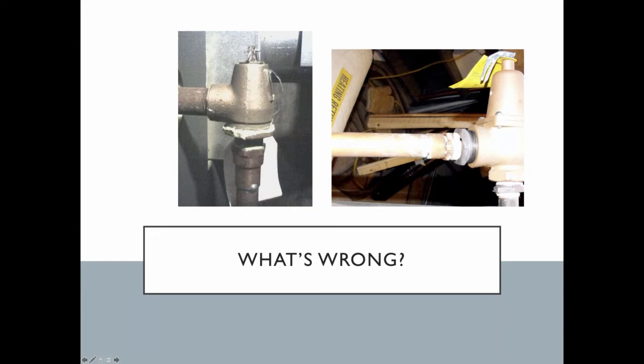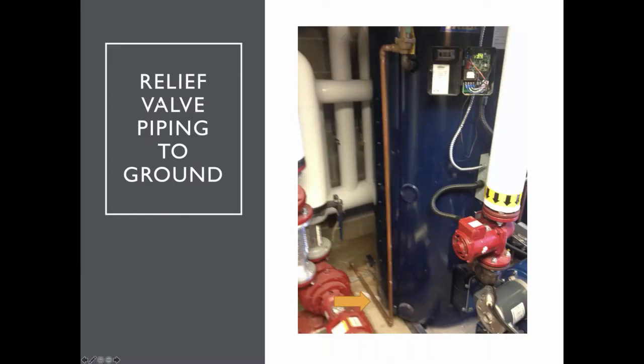And what happens is you've essentially reduced the relieving capacity of that relief valve. We had one job where they had a 2-inch relief valve on it, and then a guy bushed it down to 3/4 inch. I asked him, why do you have a 3/4 inch on there? He said, well, I didn't have any 2-inch, and he just thought this was okay. This is not okay. So look for this and find us on the jobs.